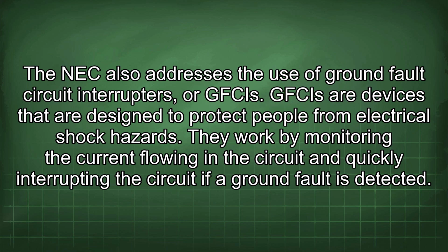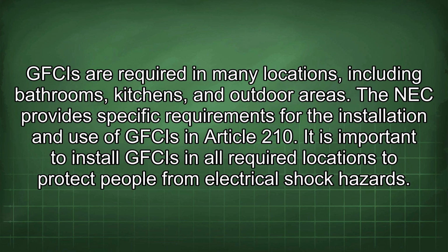They work by monitoring the current flowing in the circuit and quickly interrupting the circuit if a ground fault is detected. GFCIs are required in many locations, including bathrooms, kitchens, and outdoor areas. The NEC provides specific requirements for the installation and use of GFCIs in Article 210. It is important to install GFCIs in all required locations to protect people from electrical shock hazards.